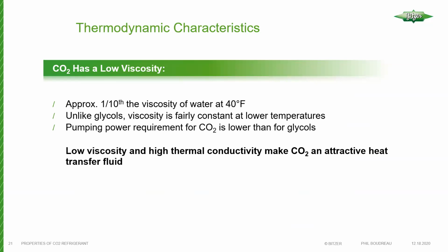CO2 also has a low viscosity, in fact approximately 1/10 that of water at 40 degrees Fahrenheit. And unlike glycols, the viscosity is fairly constant at low temperatures. So as the temperature varies, the viscosity doesn't change as much as it would with glycols and other heat transfer fluids.